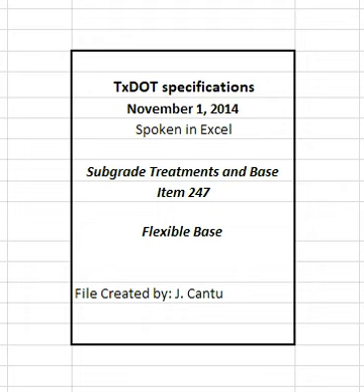2.1.3.2.3 Department furnished and allowed recycled materials. When the department furnishes and allows the use of recycled materials or allows the contractor to furnish recycled materials, the final blended product is subject to the requirements of Table 1 and the plans. 2.1.3.3 Recycled material sources. Department-owned recycled material is available to the contractor only when shown on the plans.